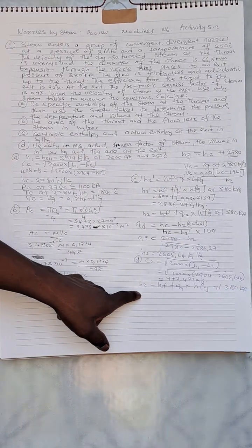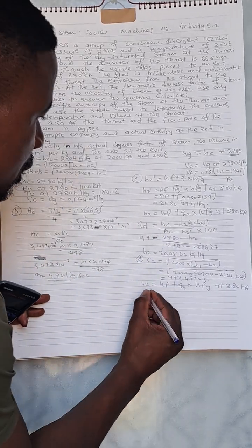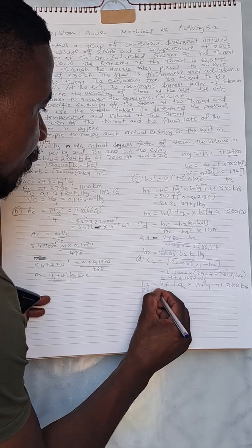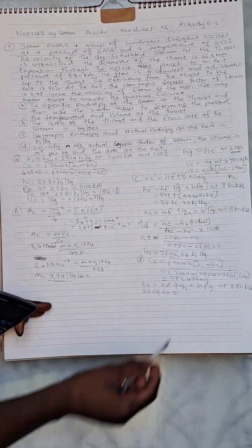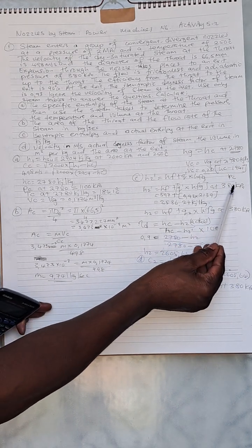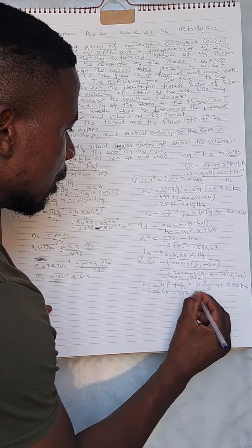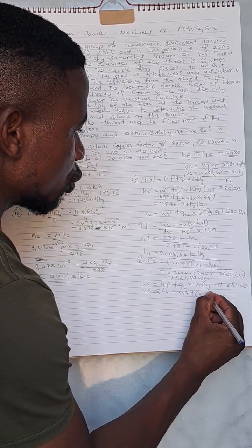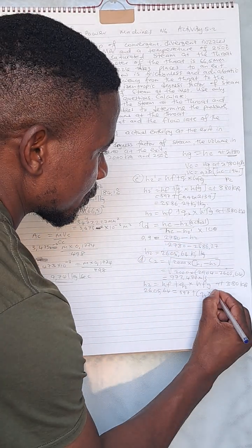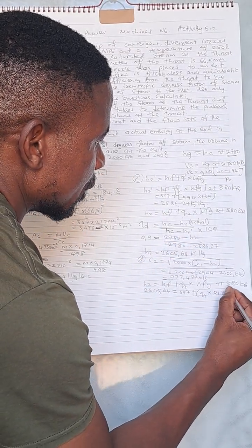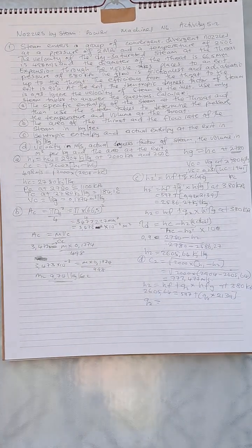So it is taking us back to this formula. Our H2, we said, is 2605.64 equals our HF at 380, which we already got, which is 597, plus our Q2 actual times our HFG, which we got as 2139.